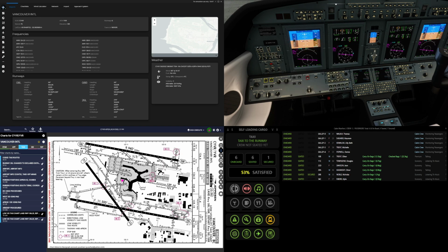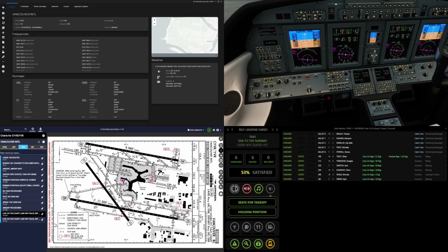Now that can go away. Flight director is on. Nav mode can come on. Vertical speed. We will climb at probably 1500 for starters. Let's set the altimeter. Altimeter is set. Now let's take a look at the takeoff performance and see if...